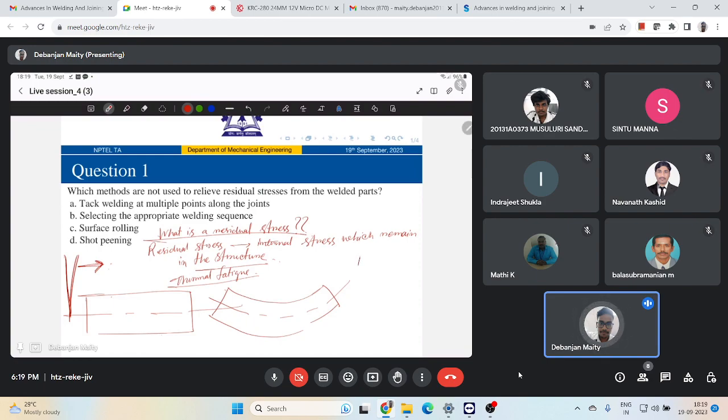You may have heard of a process called laser forming. Laser forming is a technique where you can form your metal surface through the heating and cooling method. Now, what is happening here? If you are heating a material, let us say this was my workpiece and this is my fusion region, where I have melted the workpiece surface.